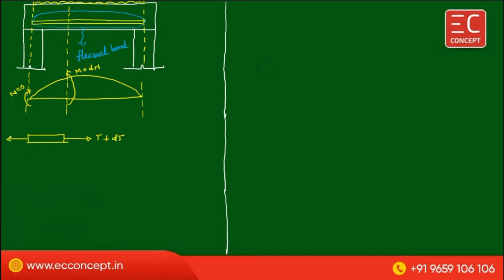Similarly here, the force corresponding to M is T. But here the T value is equal to 0 since moment is 0. Here also the T value is equal to 0 since moment is 0, plus the variation is only dM. So finally, this steel bar is subjected to a tensile force of dT. Now the dT force which is acting in this direction is 0.87 Fy Ast.